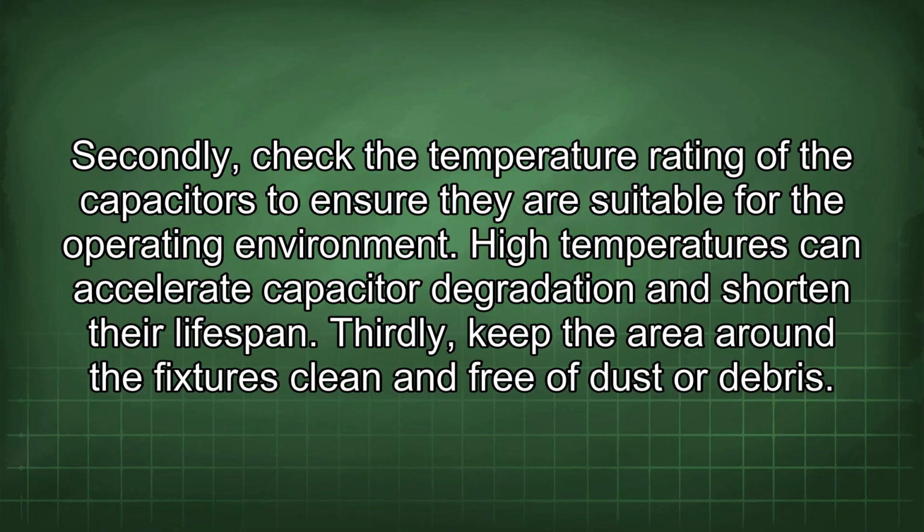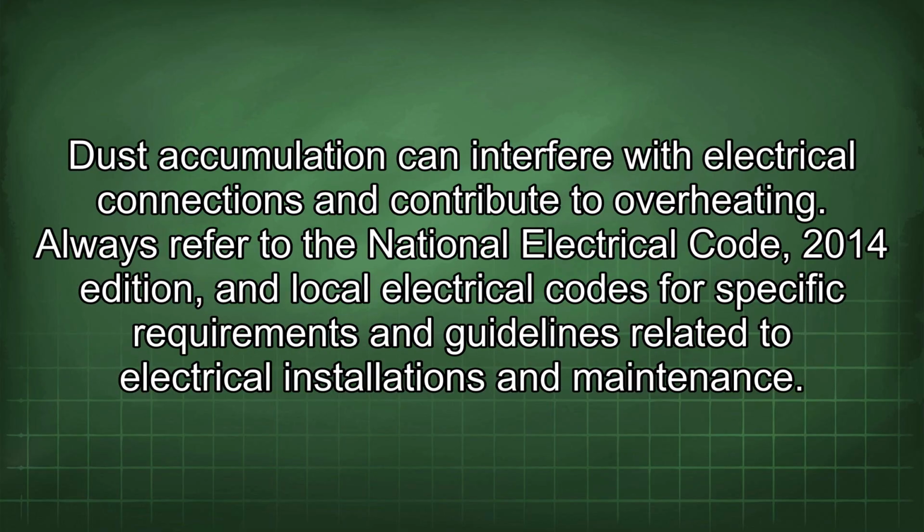Thirdly, keep the area around the fixtures clean and free of dust or debris. Dust accumulation can interfere with electrical connections and contribute to overheating. Always refer to the National Electrical Code 2014 edition and local electrical codes for specific requirements and guidelines related to electrical installations and maintenance.